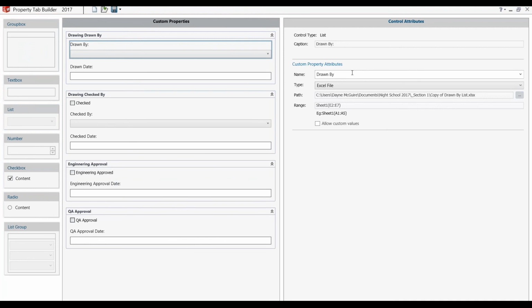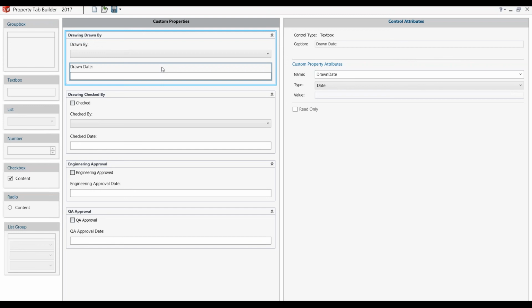So I'm happy with my sheet format. Everything is referenced the way that I want it to be referenced, so I'm going to save my sheet format. And I can do that by hitting the File button, coming in here, and the only way to do that is hitting that Save Sheet Format button. So I'm going to come in here, grab my sheet format, give it a name,